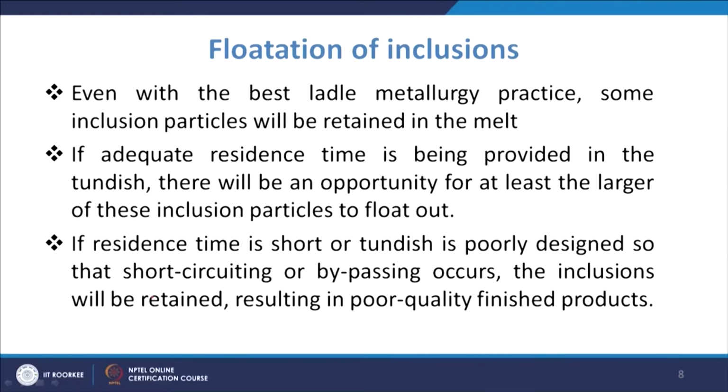If the residence time is short, or the Tundish is poorly designed so that short circuiting or bypassing occurs, the inclusions will be retained, resulting in poor quality finished product. If your Tundish is such that the inclusion residence time is very small, then the inclusions coming inside the Tundish will most likely go directly towards the outlet, and from the Tundish outlet to the mold.